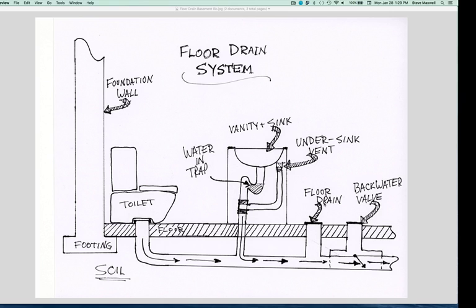So starting with the floor drain, the first thing I want to bring your attention to is this thing over here called the backwater valve. As I've explained in the course, this is a fancy sort of one-way valve. It lets sewage leave your house, like you see here, but it prevents sewage from coming back up into your house and bubbling right up through the floor drain and filling the bottom of your basement with your sewage and other people's sewage too. Now, this sort of thing happens to thousands of homes each year when municipal sewage systems are overloaded, usually because of a lot of rain.